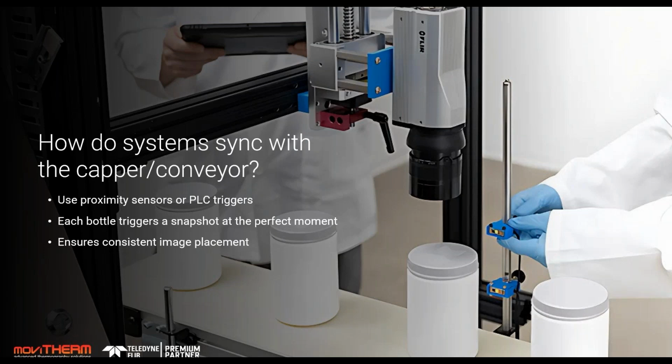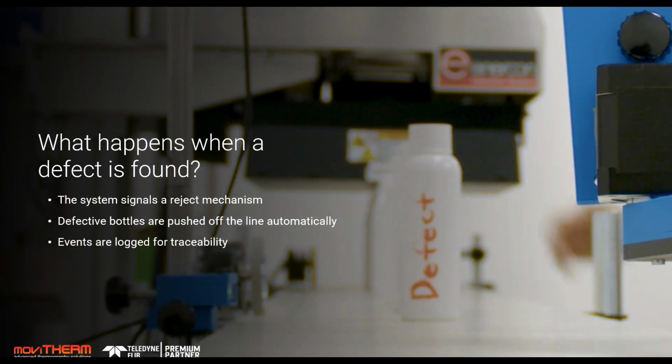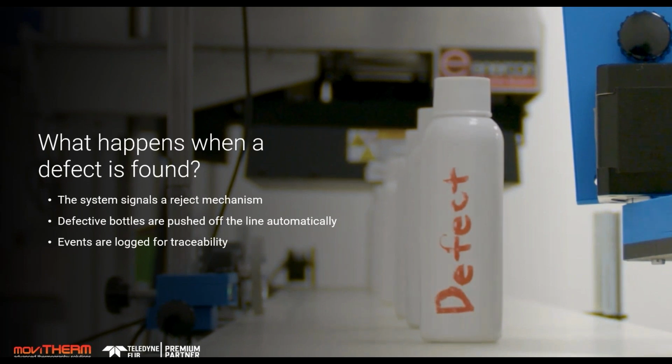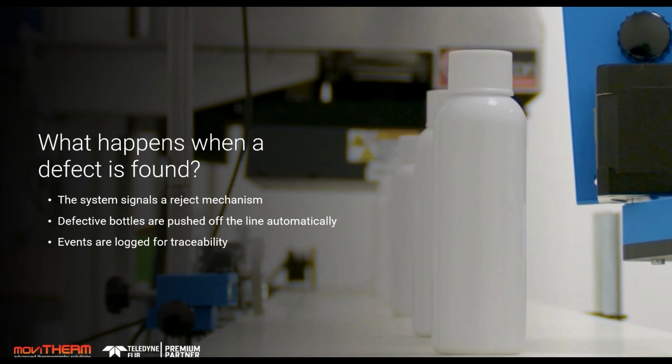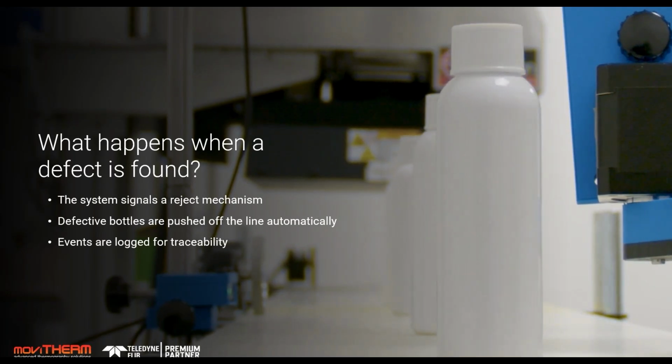So I guess as this system is running and it's looking at all these different caps, what actually happens when a defect is detected? Is there some way to do a reject process automatically? Yeah, so we have a computer that's running our application, and when we get a failure, the PC process is maybe 75 milliseconds or so for us to take a look at the image, process it, and figure out if it's a pass or a failure.